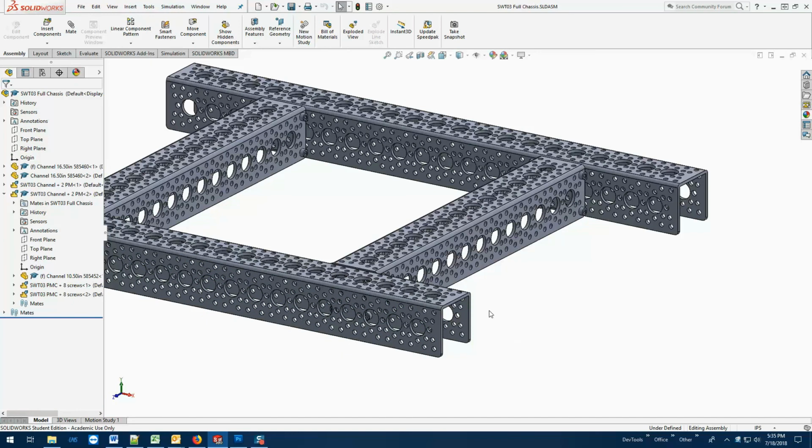We're going to need maybe a spacer or two on either side. We are definitely going to need a collar or some other kind of stop on the far end. We're going to need a hub on this end that matches our shaft diameter. So you're probably going to use 0.25 shafts. So you need to make sure you use a 0.25 hub.